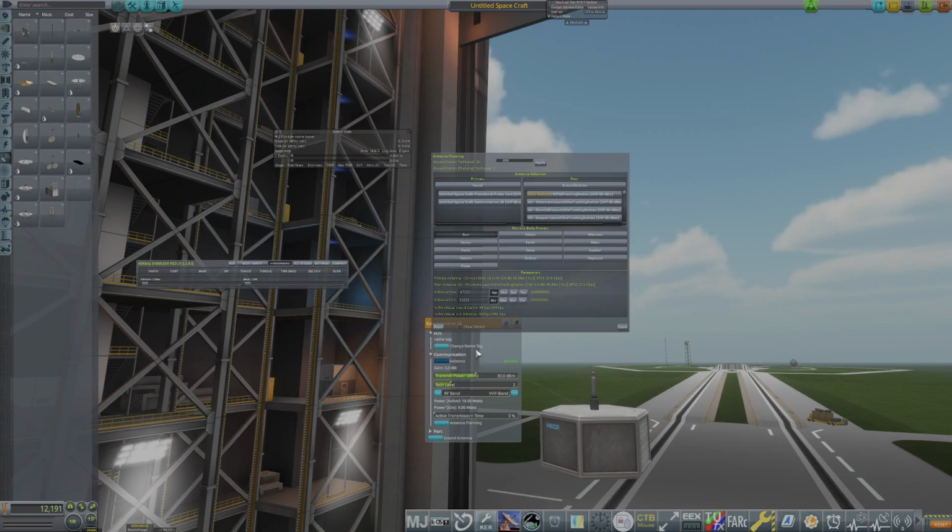The question is, what antenna do I take for that spacecraft now? It will be further away from Earth, so the beam angle doesn't really matter anymore. Then the only thing that really becomes important is the distance and the bandwidth. The question here is, do I need that bandwidth? Like if I'm just transmitting temperature data or barometric data, I probably don't need that much bandwidth as I would with other experiments. But let's say we want to keep this as early tech as possible. What antenna do we usually take?